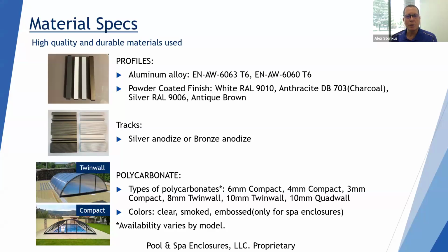Polycarbonate, we use that polycarbonate, and again, that's 200 times stronger than glass, virtually unbreakable. It's UV protected. We use that if it's a full enclosure, that twin wall, which in itself is translucent, and being translucent is going to be obscured. I kind of equate it to the old showers where you can say, well, I can see somebody in there, but I can't necessarily make them out. But that twin wall is exactly that.